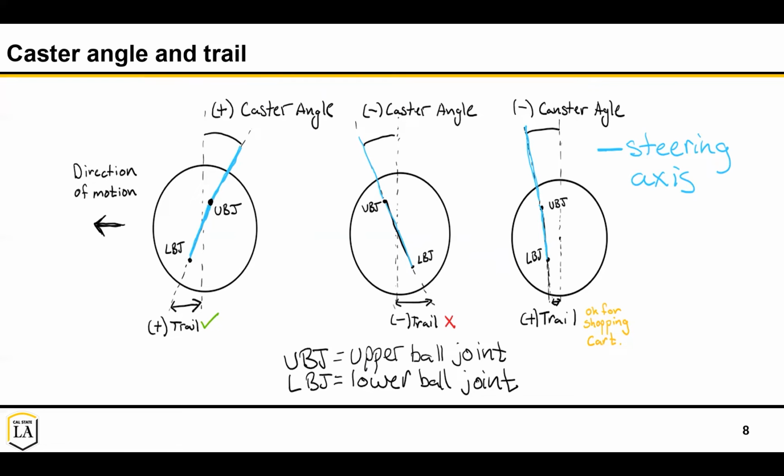What that helps do is, because your inside wheel in the turn is going down into the ground, it's going to actually help provide some load transfer from your outside wheels to your inside wheels, as you're effectively rolling your vehicle into the turn with this caster. And that'll help counteract some of the weight transfer that's inherent in a turn, which hurts your overall traction.